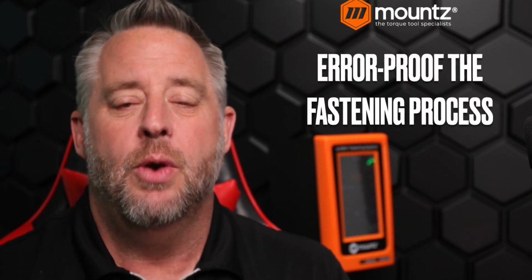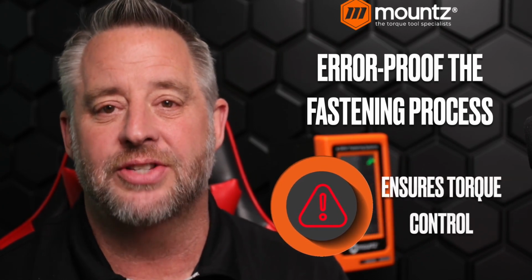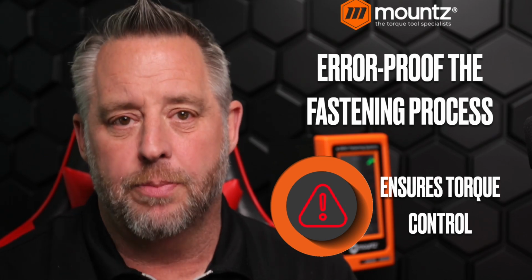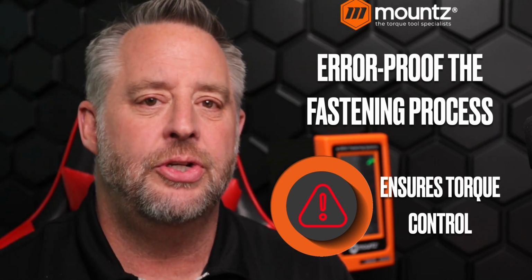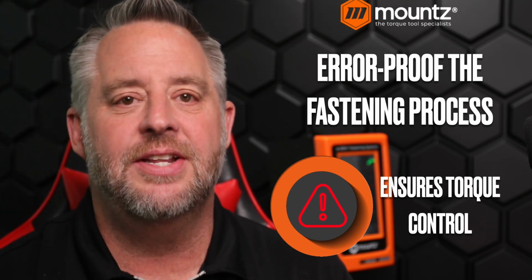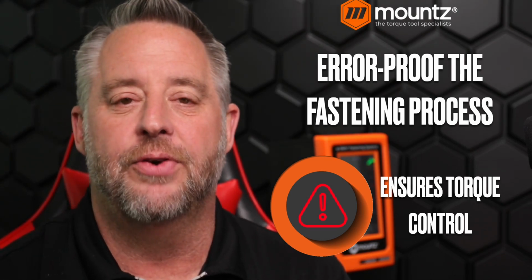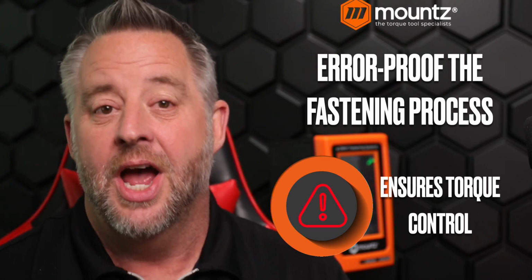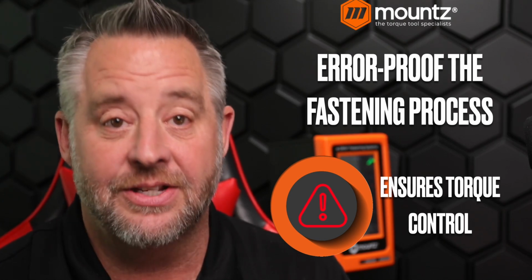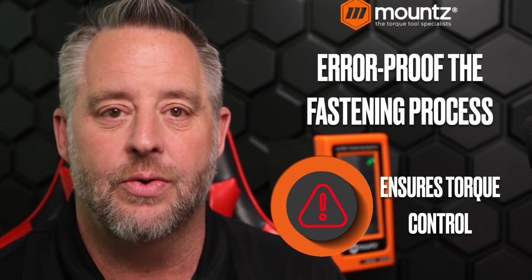And our first one, we kind of touched on it slightly, and that's going to be to error-proof the fastening process. Now, the Poka-Yoke philosophy of error-proofing is the opportunity given to the operator not to make a mistake. And we see this in everyday life, from trying to start a car. We must have our foot on the brake when we press the ignition to start the car. We also see it when we are pumping gas into our car. The nozzle must be fully inserted or the gas pump is not going to function.